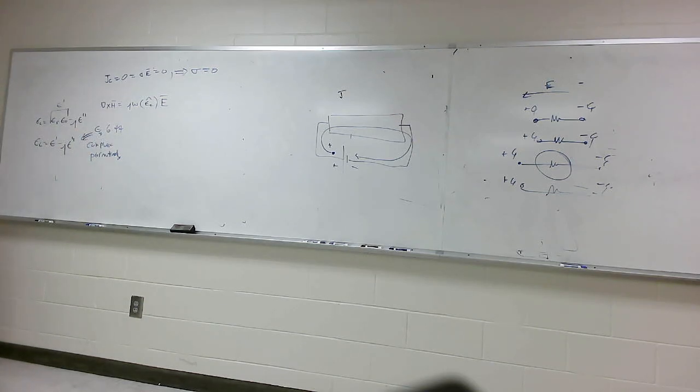Now, how does this actually work? I want you to watch over here and you'll see it. Remember, complex permittivity has epsilon prime, which is epsilon relative epsilon naught, just like the normal epsilon. But then there's this minus j epsilon double prime, and this accounts for the actual bound charge motion where you have a loss. Just keep watching, you'll see it.